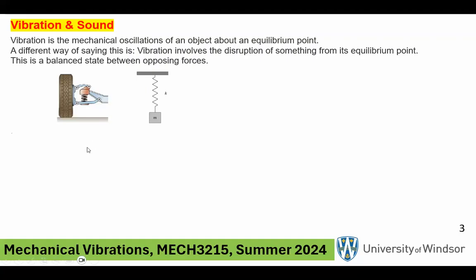For example, if you put a small load here, if you push the tire up a little bit, this setup, the suspension, resists, of course, through the structural component that you see here and through the spring that's sitting here. So that disruptive force is represented by the spring there. What you see on the right-hand side is a very elementary, basic representation of an oscillatory system that you see on the left-hand side.